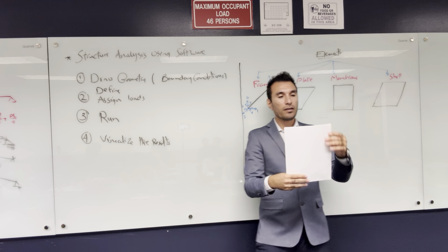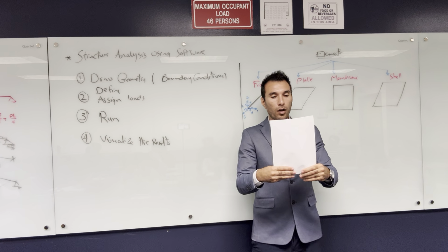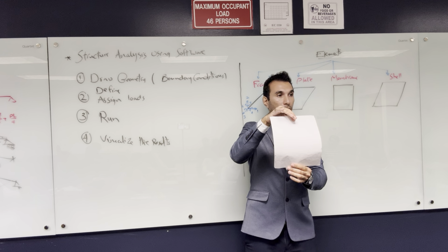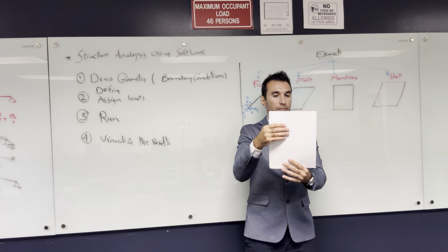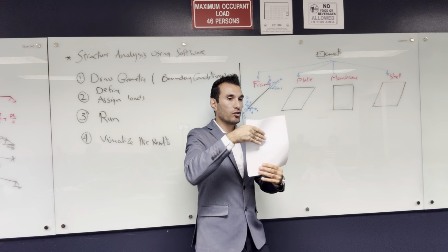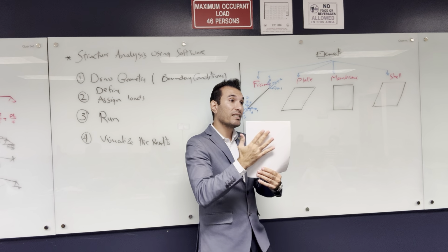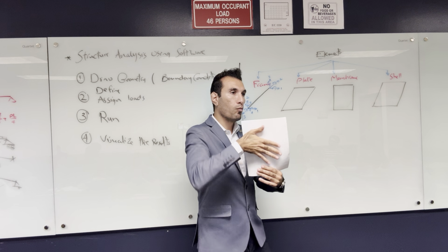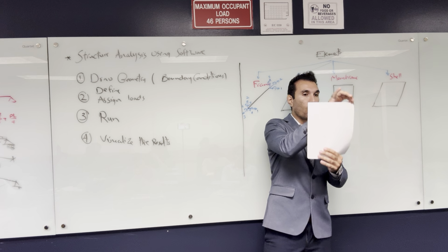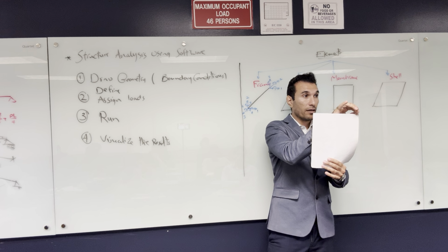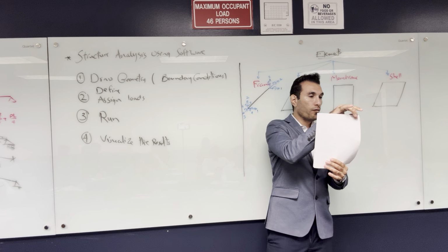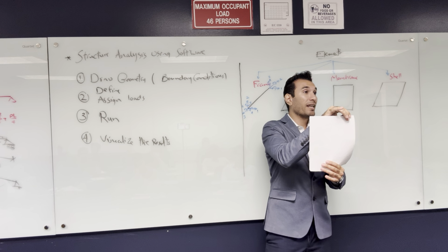The membrane is something like a shear wall. The shear wall, look at this, it doesn't bend that way, but it bends that way, because it takes most of the load in this direction, so the bending moment is that way. So it takes in-plane moment, and every point can have X and Y deformation, all right? It can move X, and it can move Y, right? But it cannot move Z.